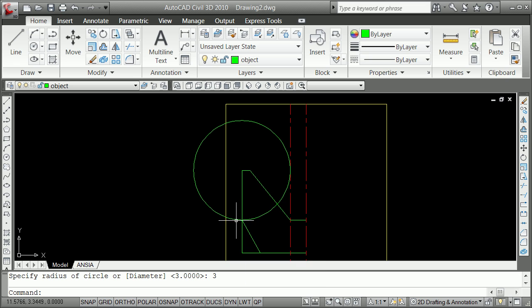And the other skill I showed was that you should be able to put any line in by clicking on a line and then using the @ command with, for instance, 100 angle minus 60 off of the standard position angle, and it would get you something really long. So you tend to draw really long things and then erase, trim, or fillet them. What I did is I drew it in the last one and then I trimmed it back.